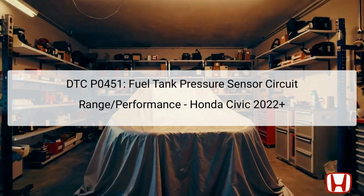The FTP sensor plays a critical role in the evaporative emission control system, EVAP, detecting pressure changes in the fuel tank to minimize fuel vapor's release into the atmosphere. The component is typically located in the fuel tank area and is pivotal in ensuring that fuel emissions are efficiently managed. Additionally, this DTC may require troubleshooting to identify any underlying problems affecting the EVAP system, and understanding its significance in the overall vehicle operation is essential for proper diagnosis and repair.